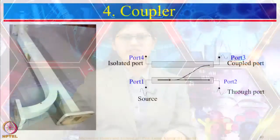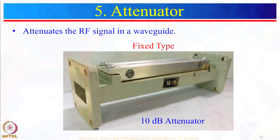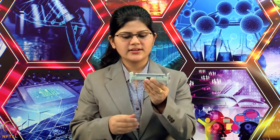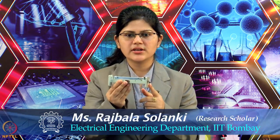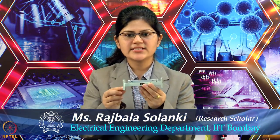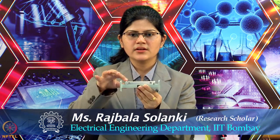Now, the next application is the attenuator. So, this is the attenuator. This is the waveguide. We will give input here and get output from here, and there is an absorbing material which will absorb the power flowing through the waveguide. This is a 10 dB attenuator. So, if we give 0 dB input here, we will get minus 10 dB output here. So, this is a fixed type of attenuator.